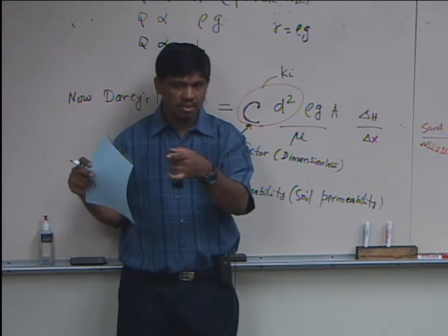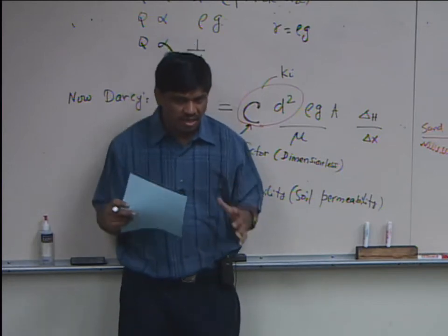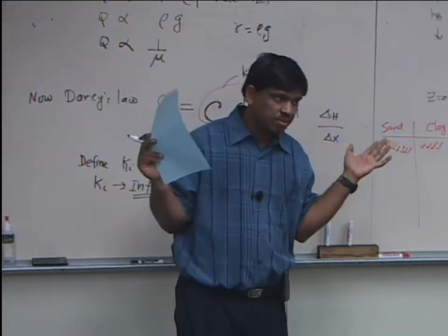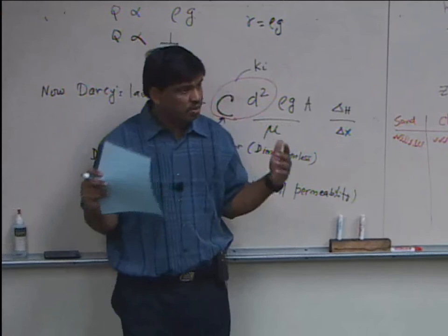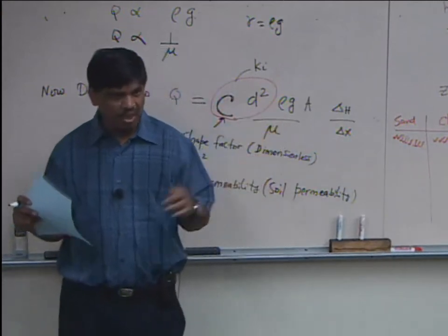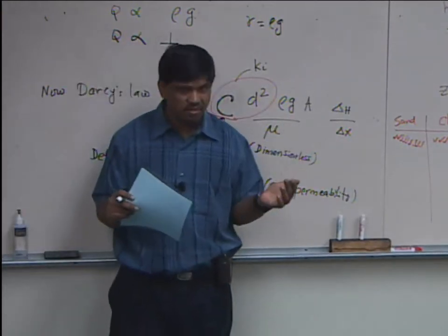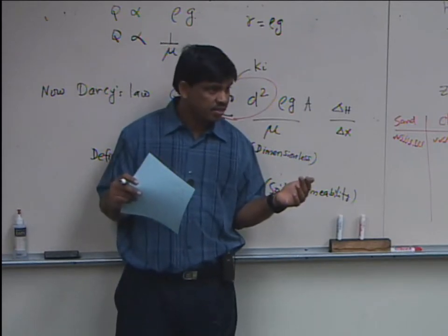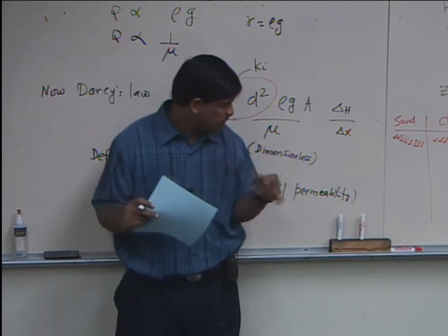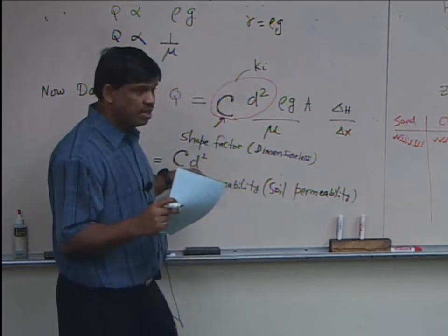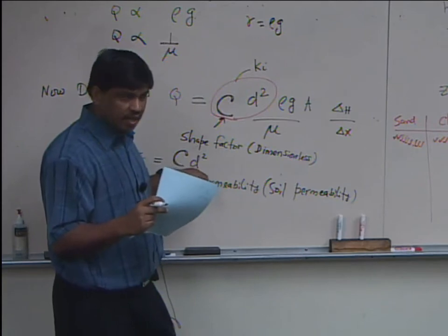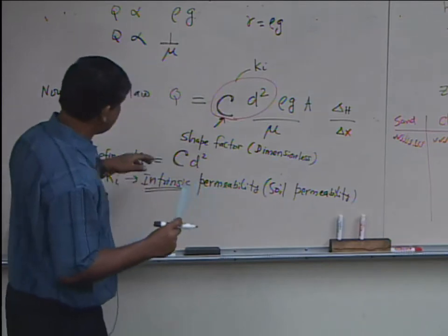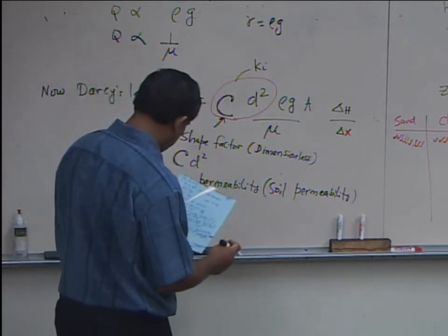Okay. Thomas. From a hydraulic conductivity point of view, we proved to ourselves that it's not a function of porosity, it's the same. Now, if I packed a column with big beads and small beads, which one will have a higher conductivity and why? The larger particle size will have a higher conductivity, based on d squared. That's right. This tells me it has to be a function of diameter, and as I increase my diameter, the hydraulic conductivity is going to go up. Actually, I have not defined hydraulic conductivity yet.